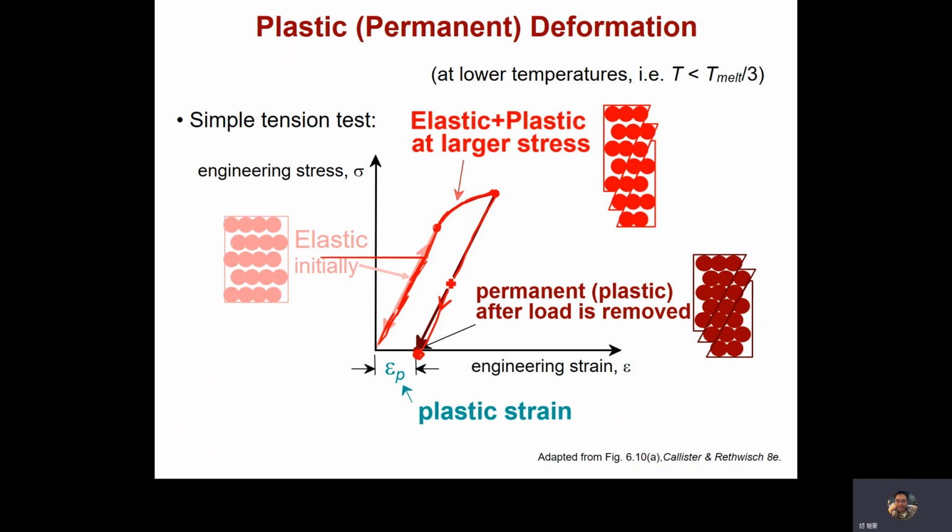And this line will be parallel to this linear elastic region. And this distance we call the plastic deformation or plastic strain.